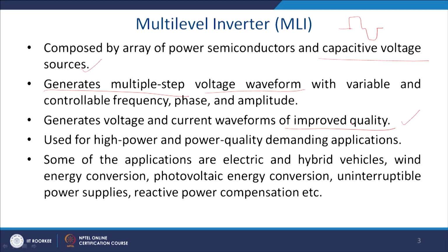So, it can have varied operations. You can have an active rectifier, and that can be made a shunt active power filter anytime, because topologically they are not different. Once you take power to the grid and convert the shunt active power filter to charging a battery, then it becomes an active rectifier.